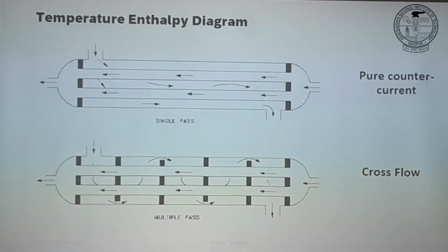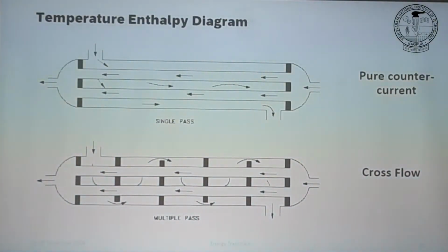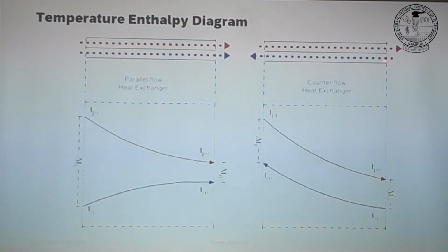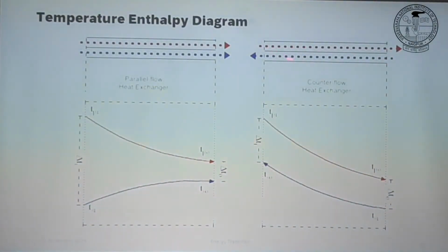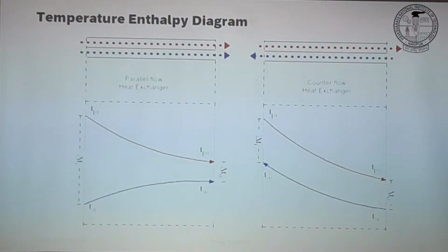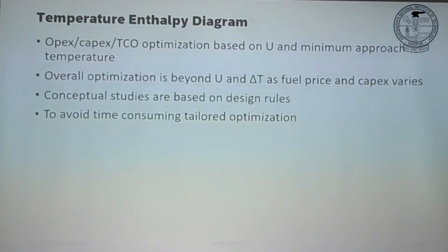Sorry, I forget to change the heading sometimes. So we saw here that's pure counter current, right? You enter here, you exit here, you enter here, you exit here. So it's purely counter current. At every point, the hot side and cold side fluids are flowing in opposite direction. But in reality,